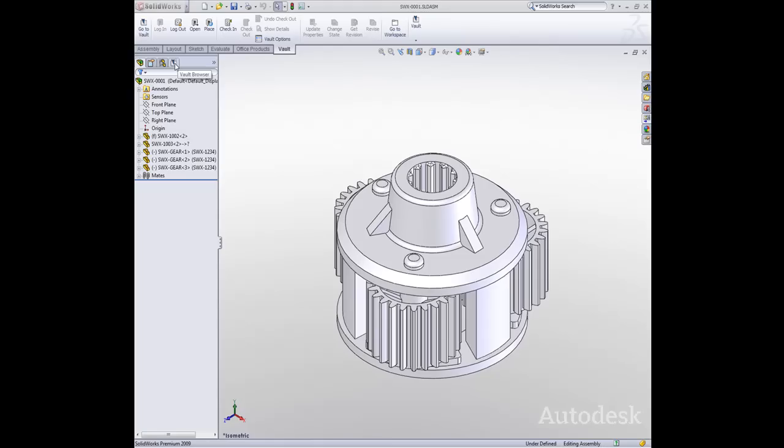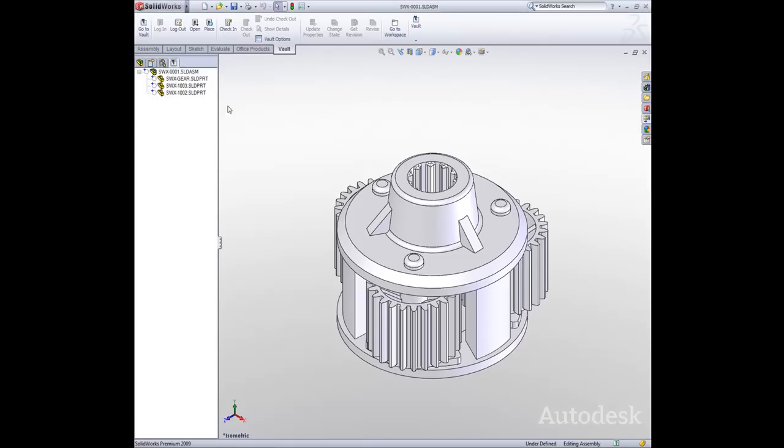What this allows us to do inside of Autodesk Vault Manufacturing is not only understand the files that are open on the screen, but we actually read the SolidWorks files' references and their hierarchy. So we can see that SolidWorks assemblies are made up of these following SolidWorks parts. We have additional symbols on the screen to let the user know that these files are not actually managed by the Vault at this point in time, but are just resident on a local hard drive or a network drive.